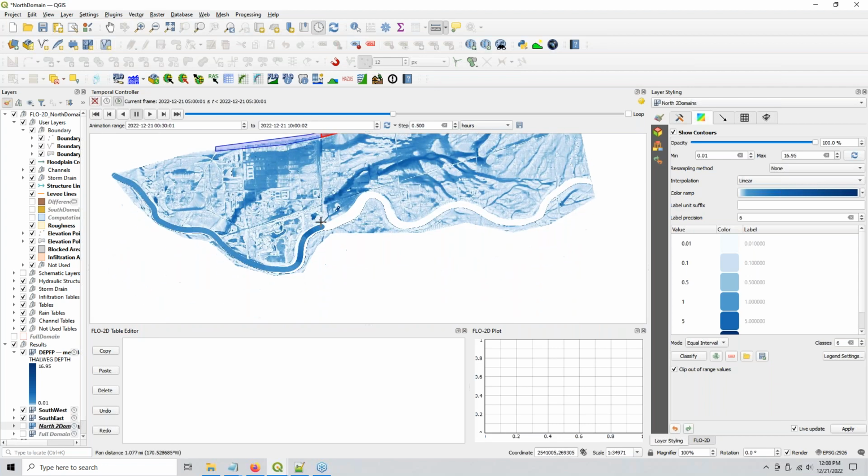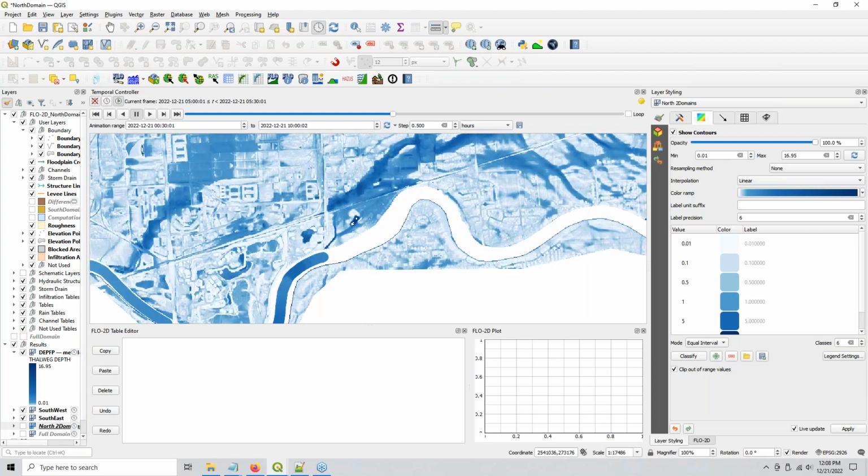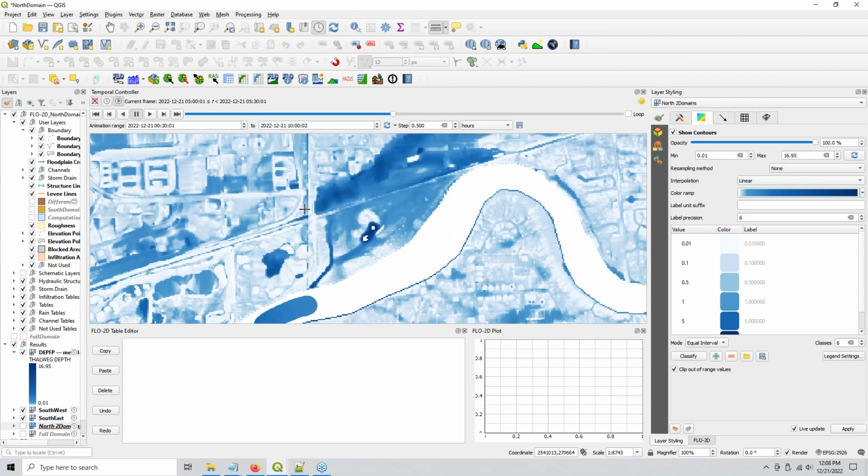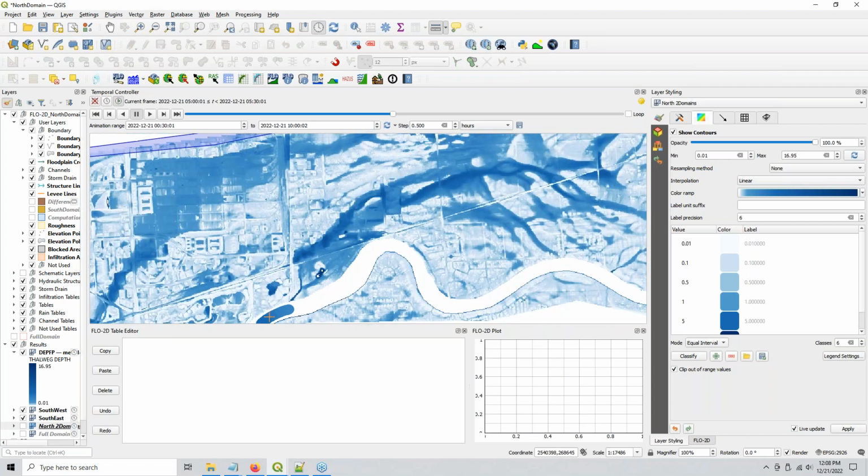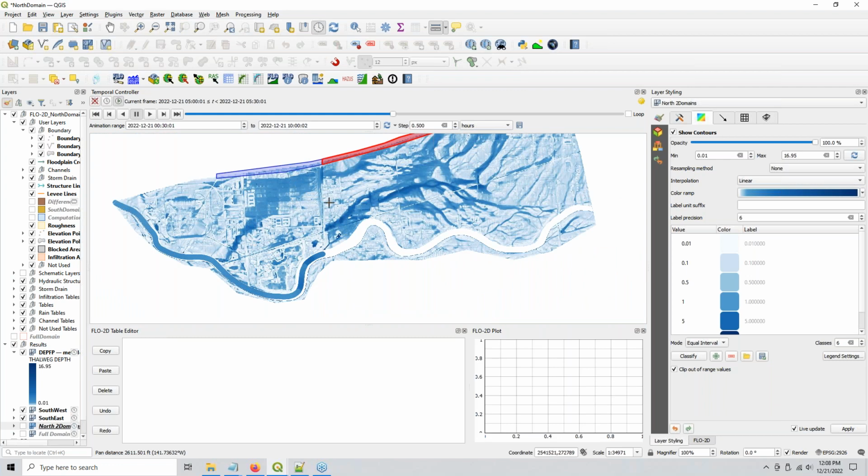Now I picked this domain exchange because this road right here blocks quite a bit of the water as it crosses the system. And there's like a natural break here, even for the channel. All of this water here was probably stored behind a hydraulic structure and needed to come down here before it could fill into the channel, and everything was in the channel as it crossed this boundary. So that was the idea of choosing this boundary as the boundary marker.